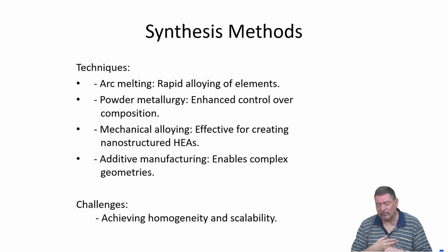Mechanical alloying is basically the same as powder metallurgy, just going a little bit more to the extreme, right? So you basically put more kinetic energy into your powders so that you store more defects, and that means that you normally arrive at a structure which has more defects and has formed more grain boundaries per volume, so you get something like ultra-fine grained or nanostructured materials.